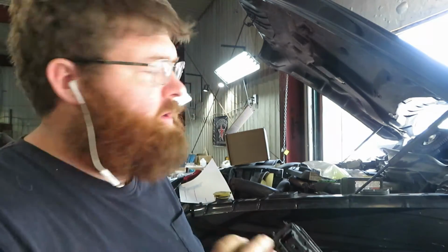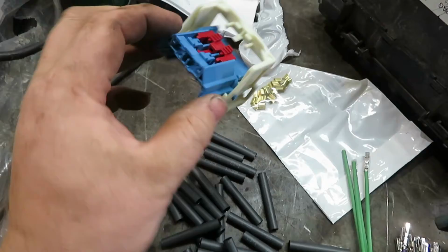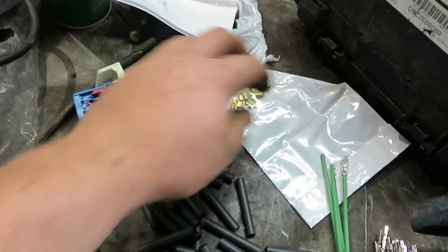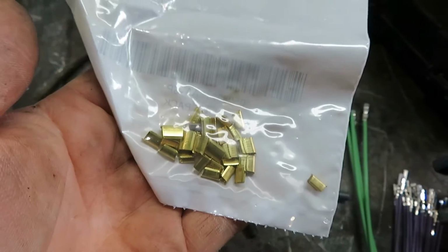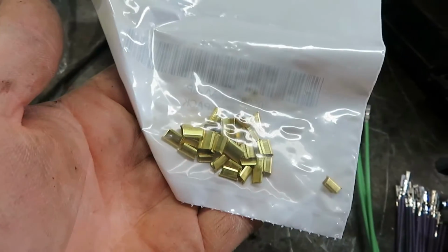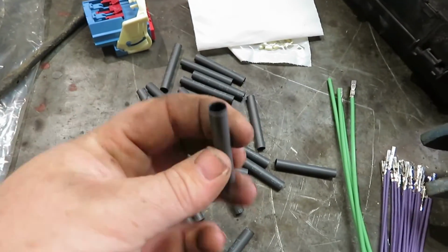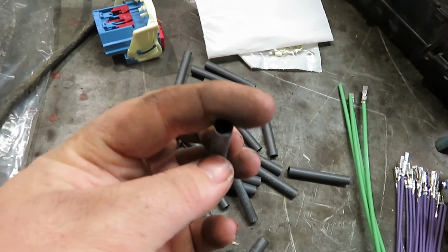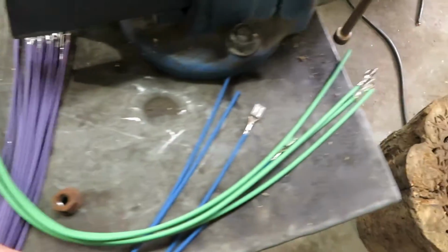But first, we got to replace that blue connector, so C130, with the repair kit. So here's everything that comes with the connector repair kit. You have your connector. You have these little crimp connect things. So you strip both wires, crimp it together, then you can fill that with solder. It comes with all the shrink tube, which is dual walled, so it has the glue in it to give you a nice seal. And it comes with 3 sizes of wire.